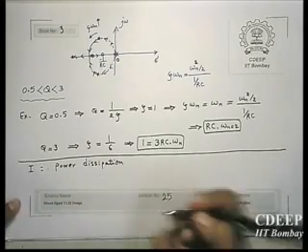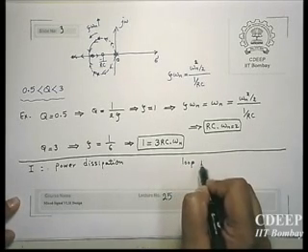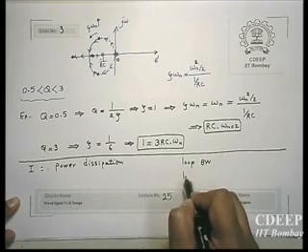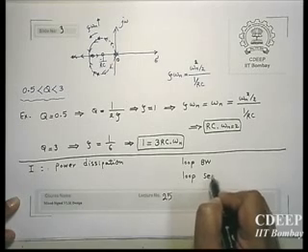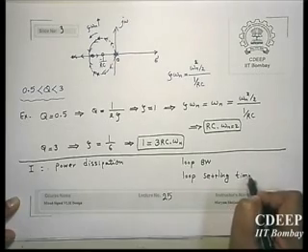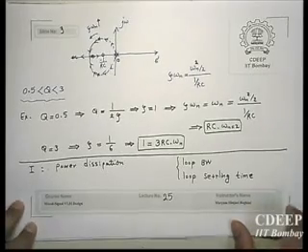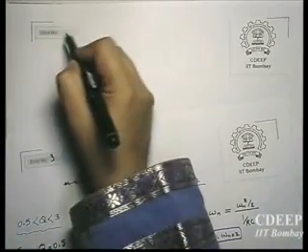Eventually, you are still worried about two things: one is loop bandwidth, and one is loop settling time. Sometimes instead of settling time, people use phase margin, the same practice we have in op-amp design. These two are the same because phase margin and settling time are similar. So again, the same trade-offs, but now with new parameters.